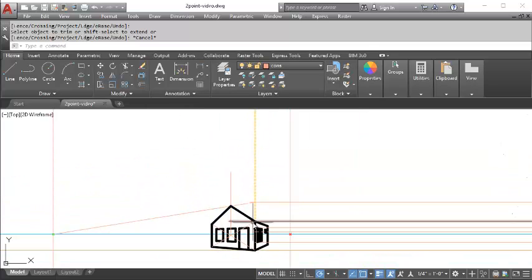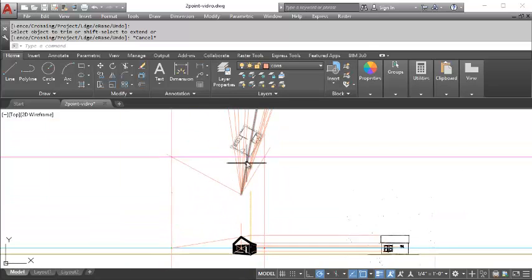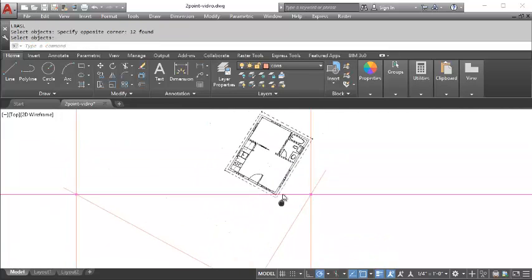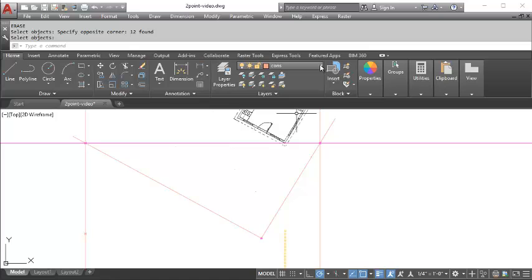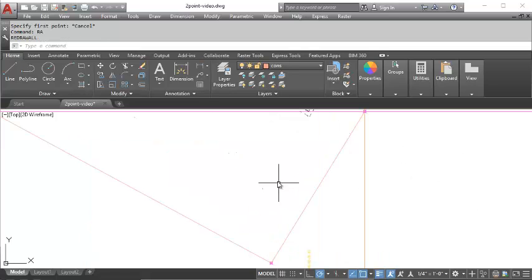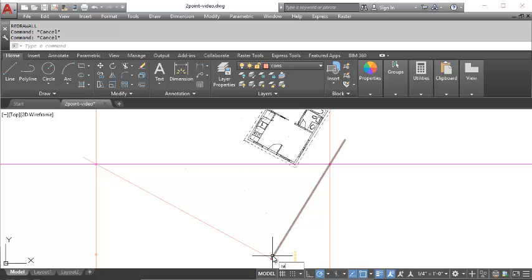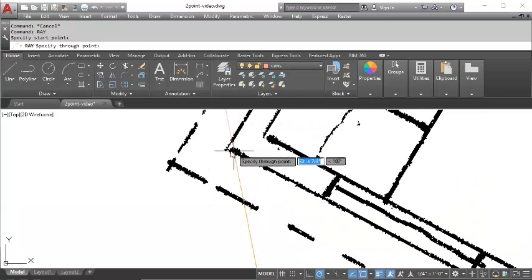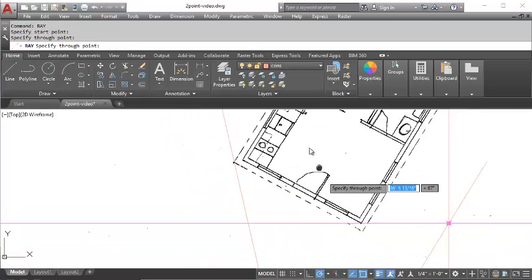So this is the gable end wall, we'd see that, but then the roof is going to hang over that. So I'm going to define the roof edges by using some construction lines again for my station point. So make sure you're on the construction layer, draw a line or a ray from the station point through where the overhangs of the roof are.